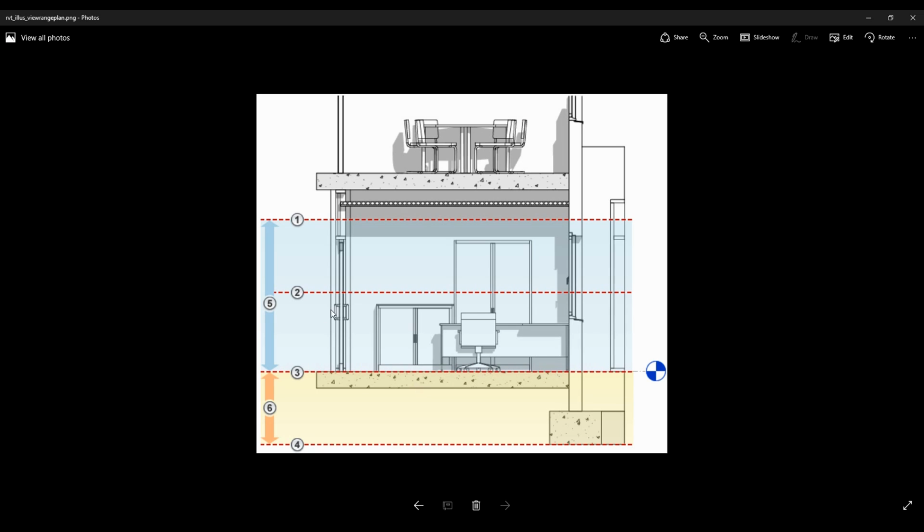And basically this is kind of what you're getting with the view range. So this is your view depth down here. And this will show all architectural and structural elements below this. This is your bottom level. Any mechanical elements below the bottom will not show up. Only architectural and structural elements will show up in your view depth. I think that's why they have it highlighted here. I got this picture off of Google, so I'm not entirely sure what these keynotes are, but